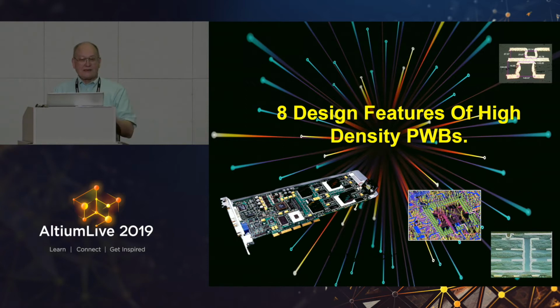So one thing I like about our industry is that we're still using technology that's 60 years old, like lands on the vias. How many of you here believe that you have to have a land on a via? Well, you all should raise your hand. You don't need a land on a via. We use lands because we used to have components we put through the holes and we crimped them and we would solder to the land as we crimped the actual lead. Well, when we went to bulk array and surface mount, we're not using holes anymore. You don't need a land.